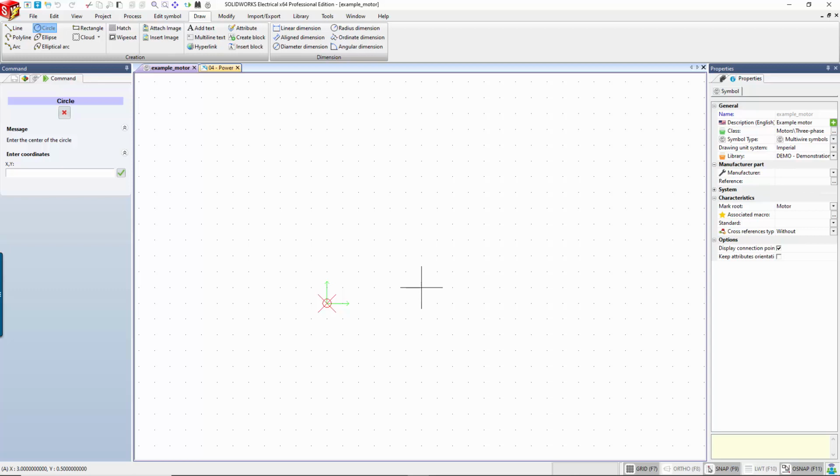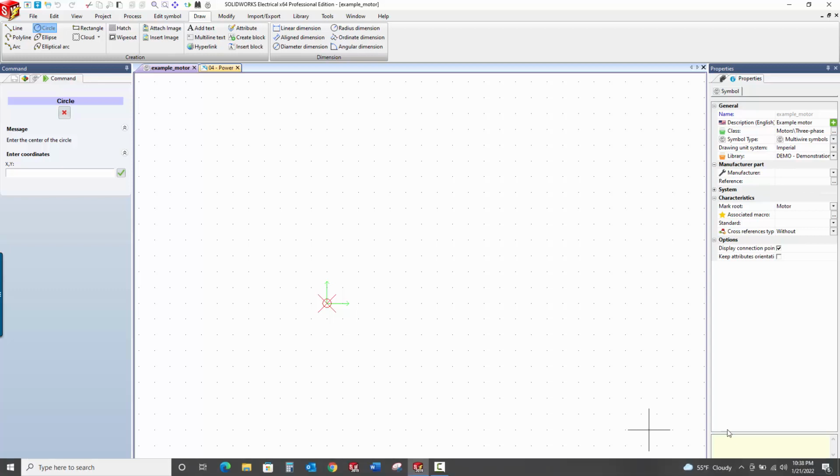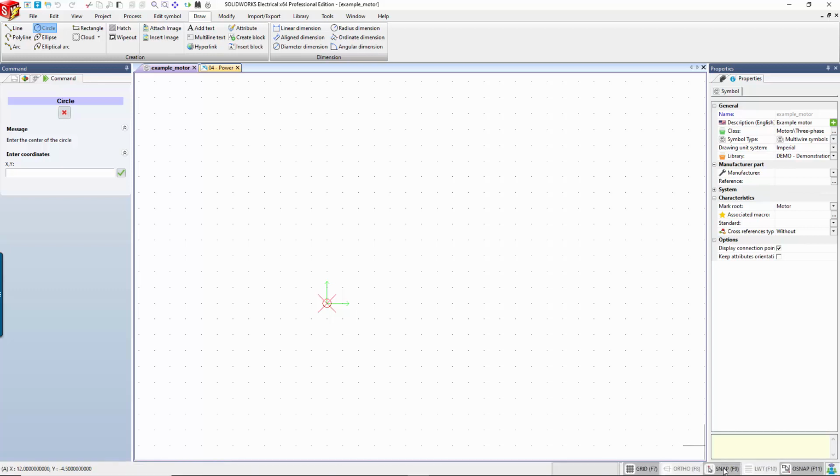And it's very important to put the connection points on some snap grid so that when you draw wires up to it, the wires can connect, and then the database knows that those wires are connected. So snaps are super important, and it will make your life super challenging if you don't keep track of that, especially when you're putting your connection points on the page.